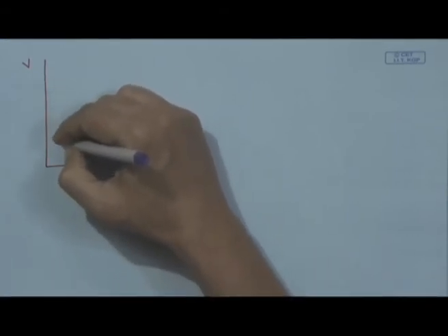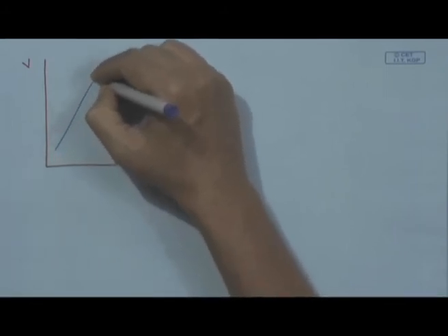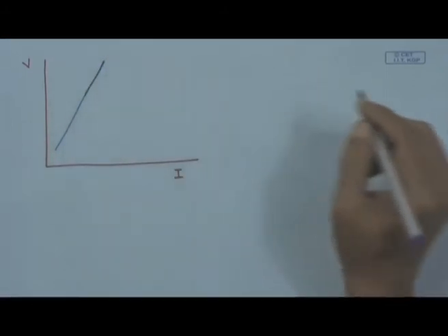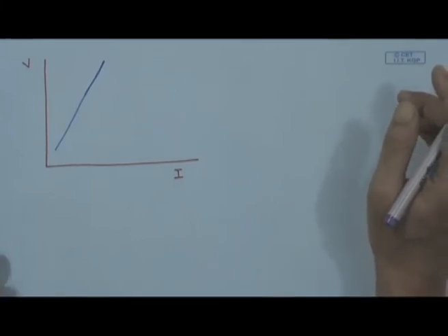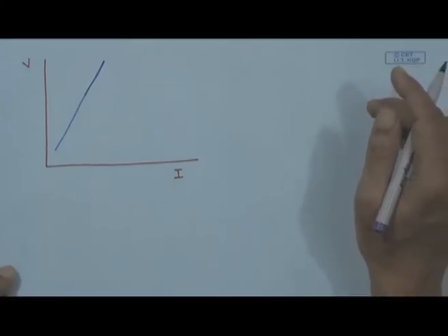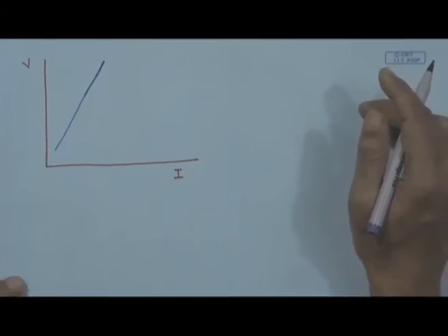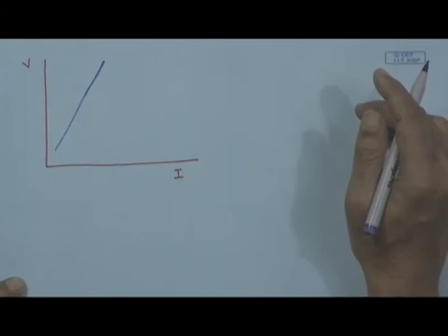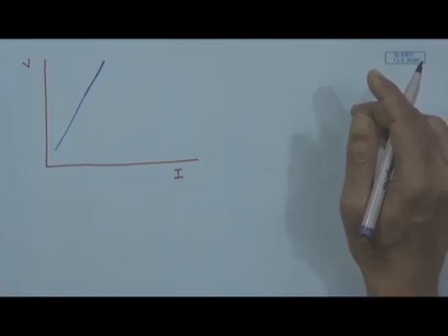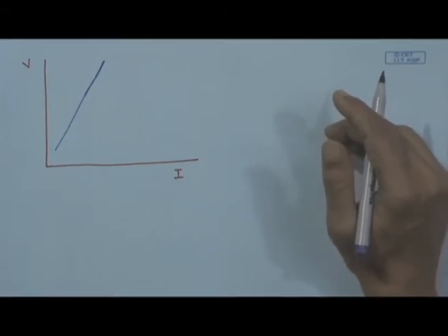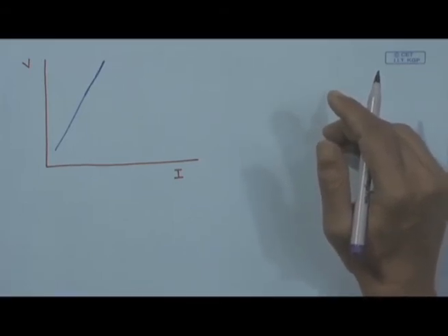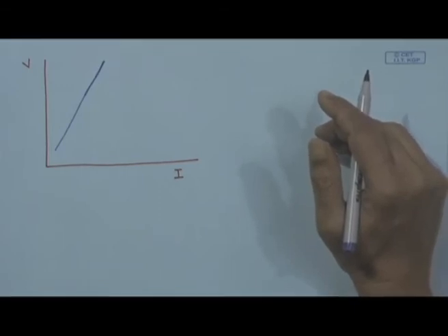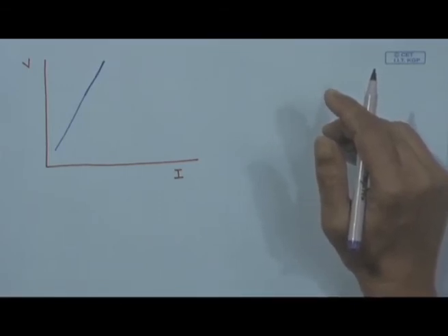Say we can draw one curve like that, and this curve is true for a sputtering device having a fixed dimension, that means fixed SOD, and just for one target material, one projectile material which is going to strike the target. All these things are fixed. So, what we are changing here is only voltage and current.